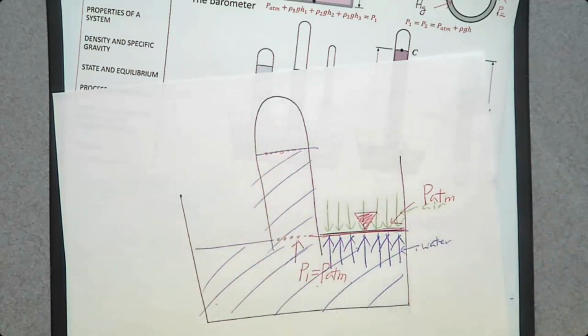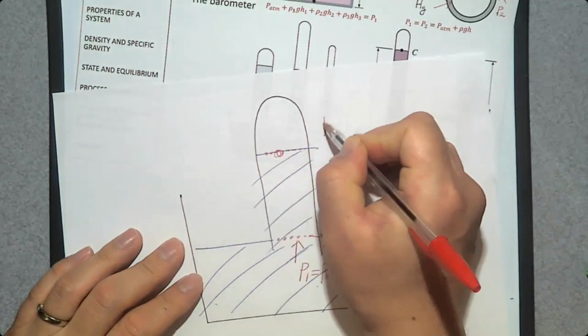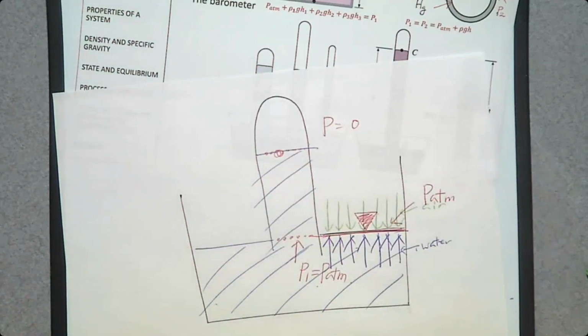Then what is the pressure by water at this interface? Zero. Even though there is water pressure, it will move up and down until it becomes zero, because there's nothing here. So at this point, pressure is zero. Now, do you remember one equation that we studied here? Delta P equals rho g h. Can you apply that here? Yes, we can.